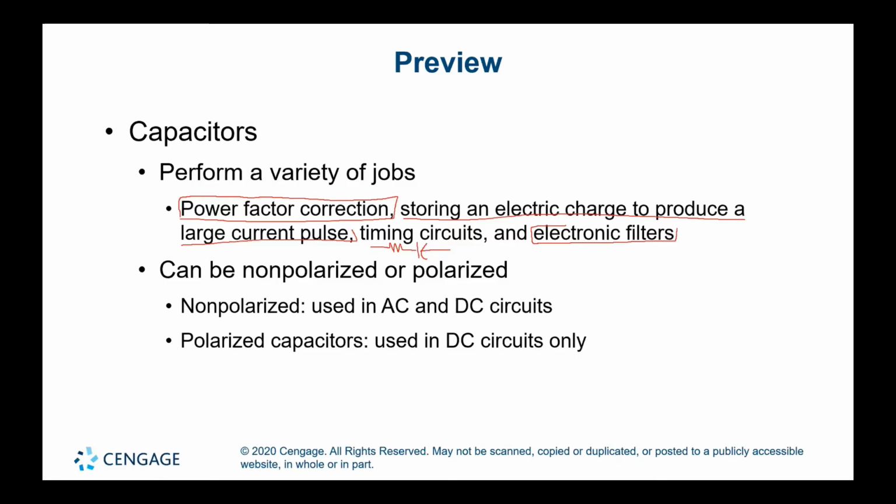So let's keep moving. Non-polarized capacitors are used in AC and DC. I already said that before. And polarized capacitors are used in DC circuits only. It's important to connect them in the proper polarity, positive to positive and negative to negative.